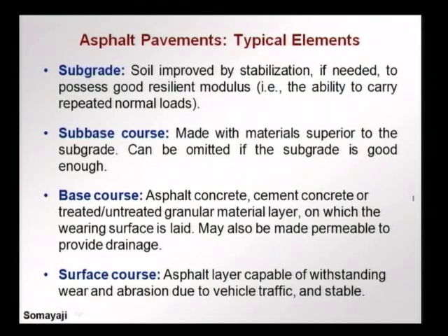So, if there is a stagnation of water in the area that the pavement is going to be built, it is a good idea to have a base course which can allow drainage and prevent water from stagnating under the surface course. So, finally, we have the top layer which is called the surface course, and this is the layer that we see in a pavement after the pavement construction has been completed.